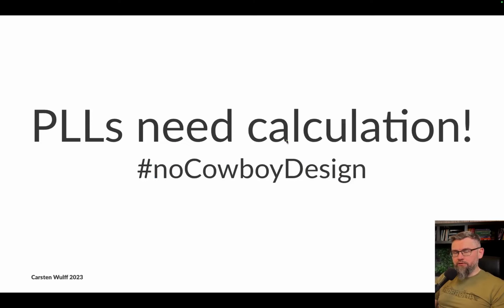But a very important point is PLLs absolutely need calculation. There is no way. Well, it's unlikely that if you just sit down and draw your schematics and try to simulate, it's going to work. Most likely it will not work, and it will be very hard to tune the different components, so the charge pump, the loop filter, the oscillator of the PLL, without sitting down and analyzing the PLL on a piece of paper or in Python or with calculation.